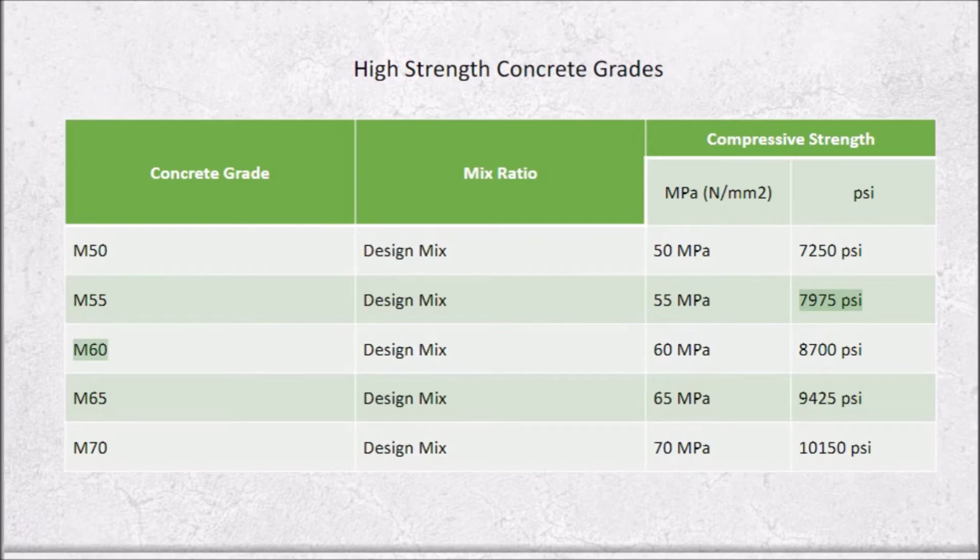M60, design mix, 60 MPa, 8700 psi. M65, design mix, 65 MPa, 9425 psi. M70, design mix, 70 MPa, 10150 psi.